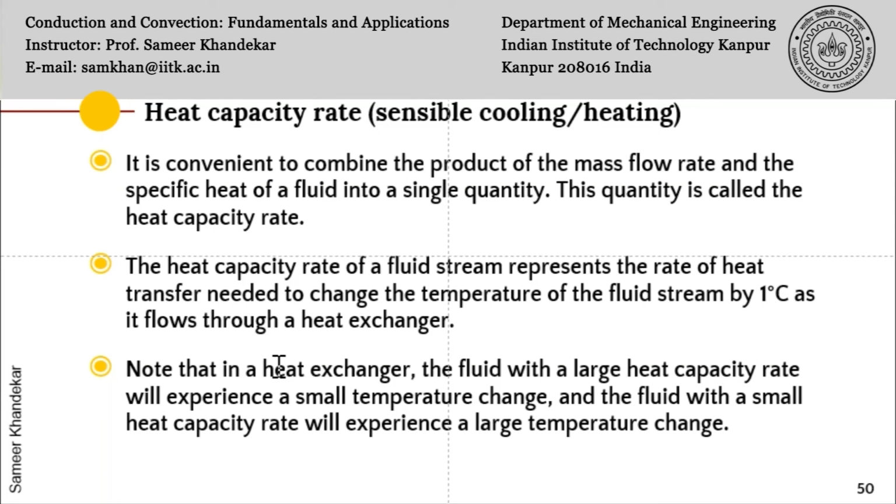So please note that as soon as you have a higher thermal mass, it is natural to say that of the two fluids, the hot and the cold, the one which has a higher heat capacity rate will have a smaller temperature change, and vice versa.